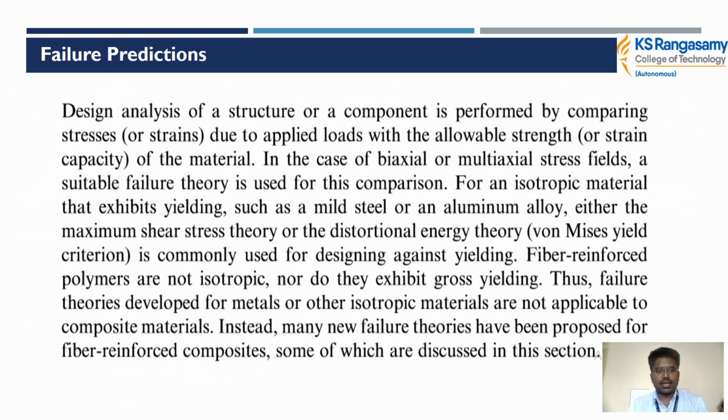Failure prediction means the design analysis of a structure or a component is performed by comparing the stresses or strains due to applied loads with the allowable strength of the material. In the case of a biaxial or multi-axial stress field, a suitable failure theory is used for this comparison. These types of failure come from the composite material, from the lamina and laminate side, and from the bonding of the fiber and resin side.